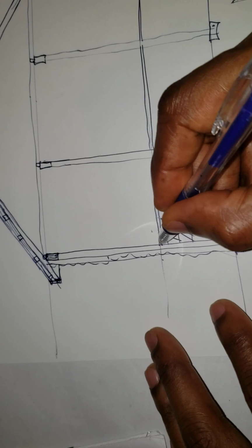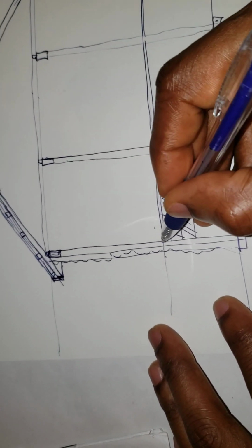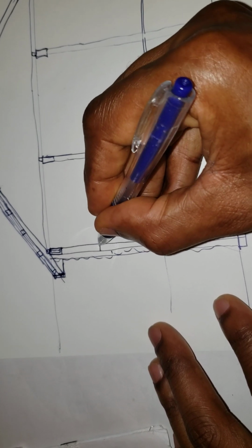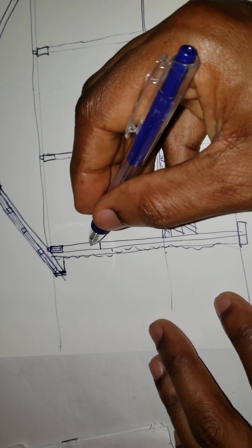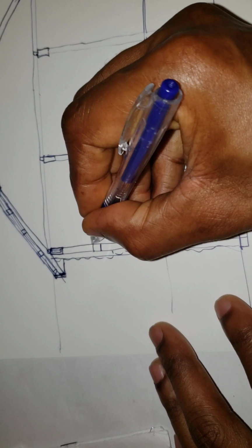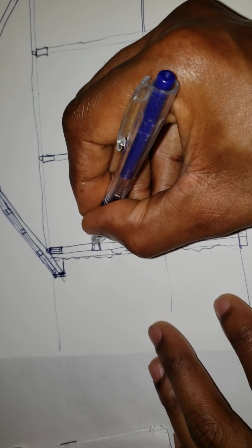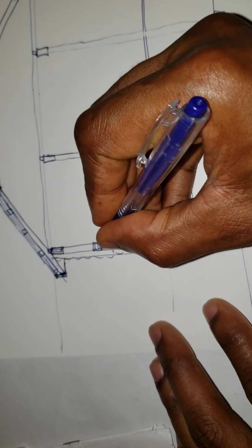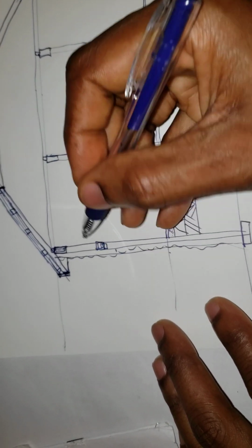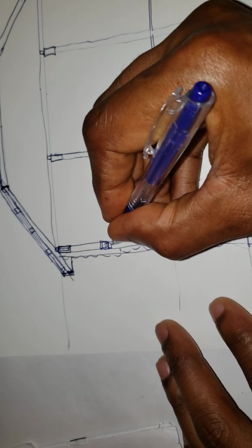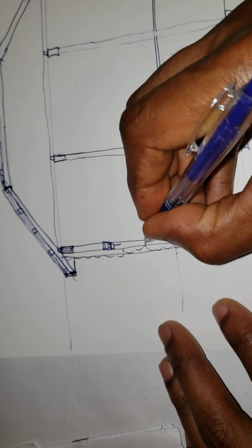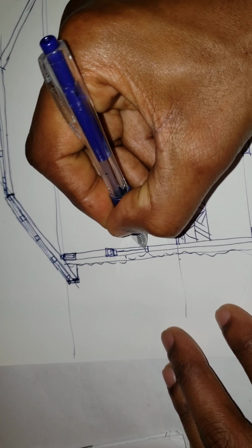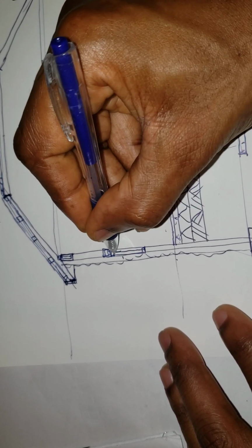Now from here we have a window. We could draw a window here. From the finished floor to the top of the window should be 2100. And above that we have the lintel. The lintel is 150 by 150. Now for the window, we would need the window framing, top of the window, sill height. And I use this for the window.